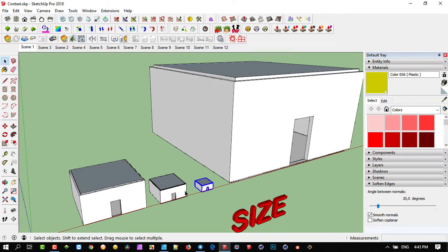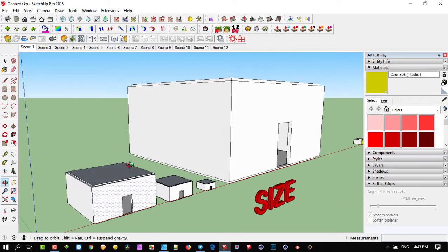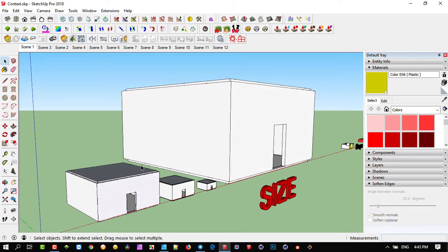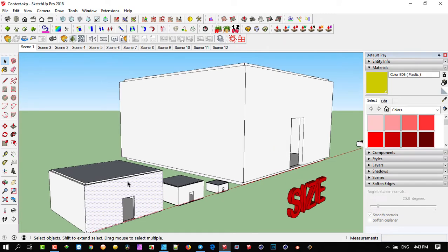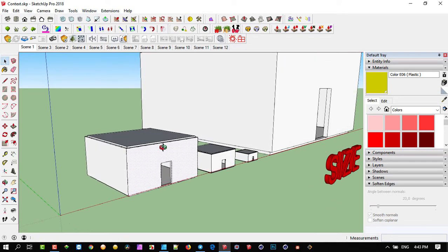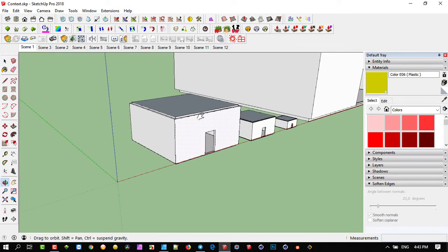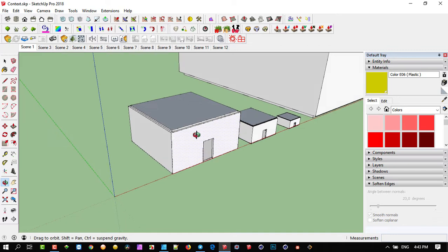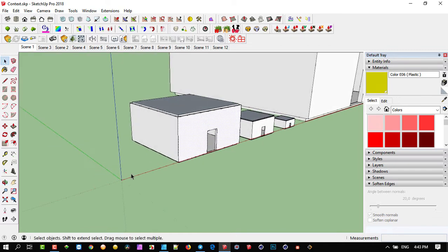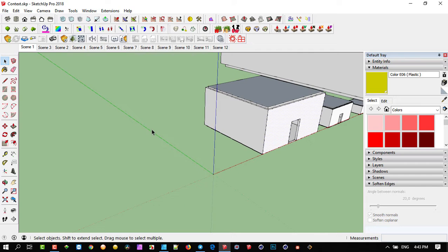But what tends to happen is if you put a light in a bigger room and it's not working that well, you will tend to just add 10 times the power of the light to light the room up. But then that is 10 times the power of the light onto the materials that you have in the model, and then you start to lose a lot of photorealism. So from the word get-go, I would suggest, instead of going the route that most people have gone, that I've also gone for a long while, where you're just drawing an sort of arbitrary figure, rather do it according to